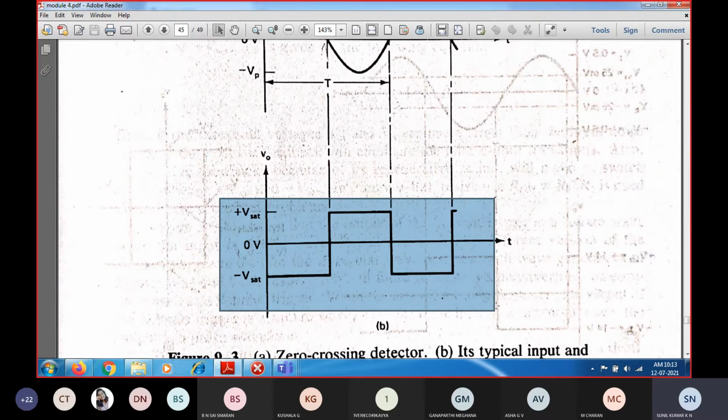So it is going to provide the same oscillator, so that all the digital circuits inside the IC will be correlated with the oscillator frequency, so that the rise time, fall time and all is going to be dependent only on the oscillator frequency for all the digital circuits within the IC. So this oscillator is going to generate the clock signal.